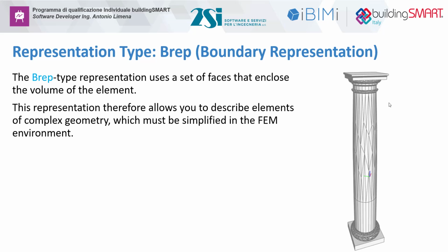The representation type BIREP, so boundary representation, as I said, uses a set of faces that enclose the volume of the element. This representation allows you to describe elements of complex geometry, which must be simplified in the FEM environment.